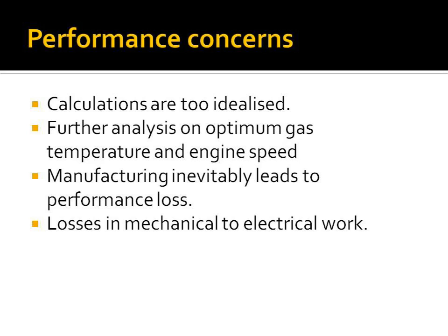Moving on to performance concerns. Four things I'm concerned about really. First, the calculations at the moment are still too idealized. The calculations assume that the expansion and compression stages of the Stirling cycle happen isothermally. However, the real engine will more than likely experience adiabatic compression and expansion.